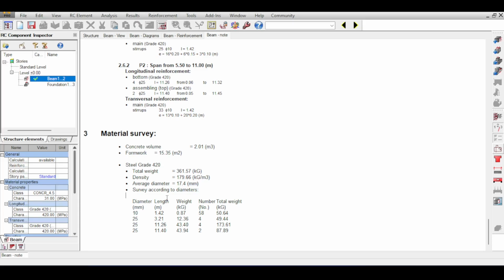Meaning, if your steel bar is 12 meters from the manufacturer, you should divide it into pieces that are able to be cut without any excess. For example, if you choose to cut your steel bars to 5 meters, if you have a 12-meter bar, this means that you can only produce 2 pieces of 5 meters from your 12-meter bar, and you will have an excess of 2 meters, and you need to think where you should put those 2 meters to avoid any loss of steel. This gets doubly important if you have excesses less than 1 meter, because it becomes really hard to use this excess anywhere, so it becomes a waste.